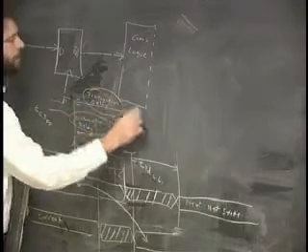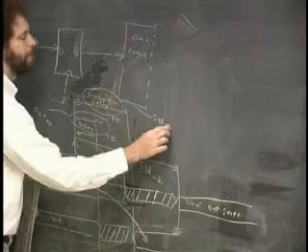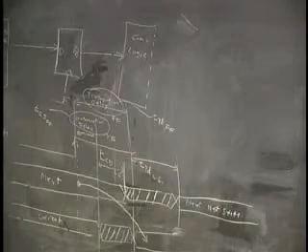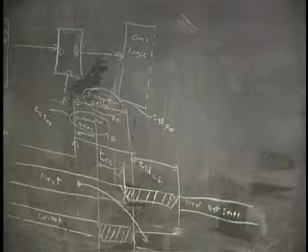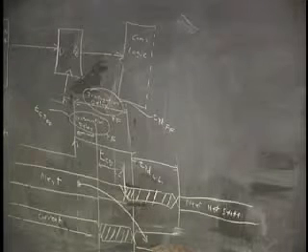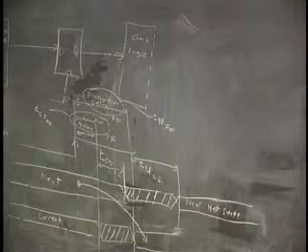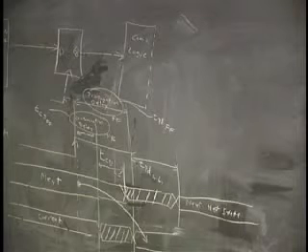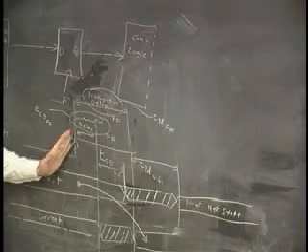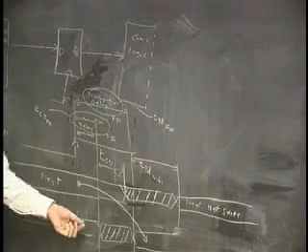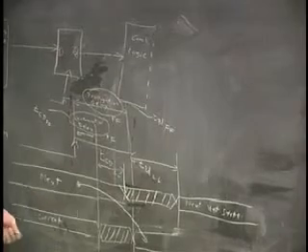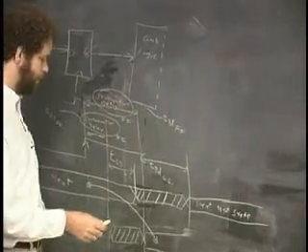And here, this is the propagation delay of the flip-flop and the contamination delay. Contamination delay is the time from when the input changes to when the output starts to change. And then the propagation delay is the time from when the input is all done to when the output is all done. And in the case of a flip-flop, we measure both of those from the clock edge. And in the case of the combinational logic over here, we measure it from when the input begins to be contaminated.